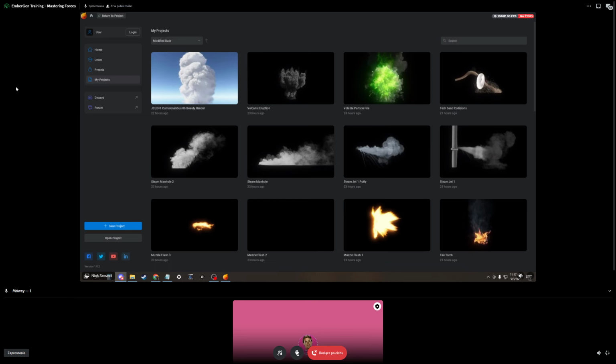But we can make this only affect particles. And so now the smoke will be exactly where the particles are, and you can create some pretty weird simulations that way. But we can make it more dynamic with another type of force. We can go over here and inject velocity from the particles themselves, and those are going to push the smoke around.